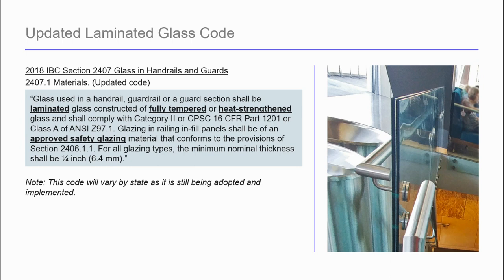There's one area of our industry, and we mentioned this before, that's recently gone through pretty sweeping changes over the past 10 years or so. That revolves around glass and spontaneous breakage. The new 2018 code has been updated to require the use of laminated glass because of spontaneous breakage in overhead conditions. So basically, they say you have to use laminate whenever there's a walking surface below, which is almost anything. So you can no longer use simply monolithic tempered glass with no laminate. And the laminate, of course, is what keeps the pieces of glass together in case it breaks.